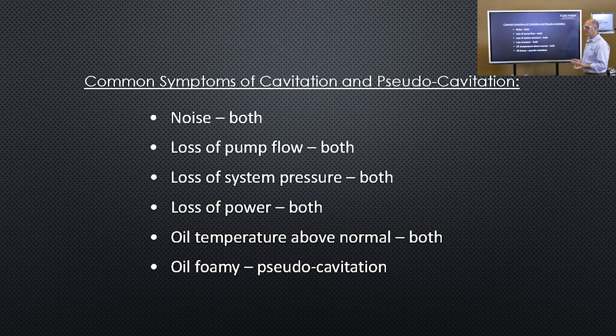So try to imagine you have a pop bottle with translucent liquid. When we take the top off the bottle, it will appear to be filled with gaseous cavities. It'll fizz. The only reason it's doing that is because when we took the top off the bottle, we released the pressure. When the pressure was off the liquid, the dissolved air came out of the liquid. Hydraulic oil is exactly the same. If we subject hydraulic oil to a vacuum, we will allow the dissolved air to come out of the oil.